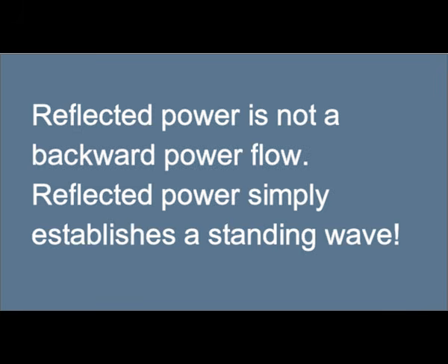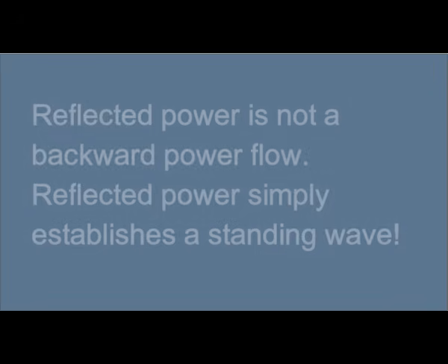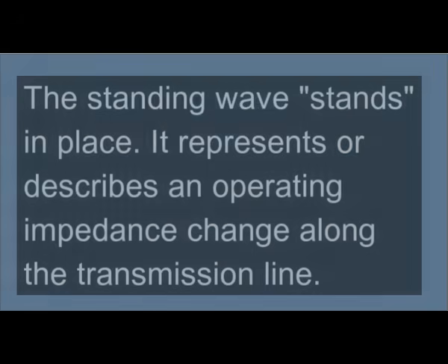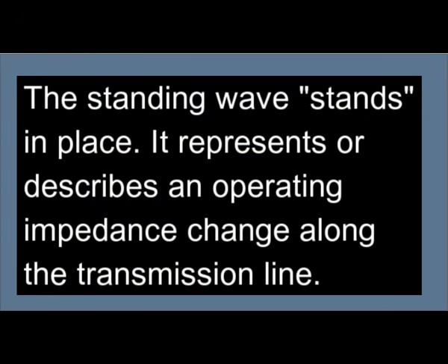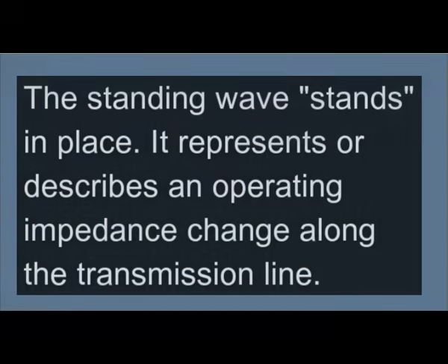Reflected power is not a backward power flow. Reflected power simply establishes a standing wave on the transmission line. The standing wave just stands in place. It represents or describes an operating impedance change along the transmission line. It's not moving, it stands there. That's why we call it a standing wave.